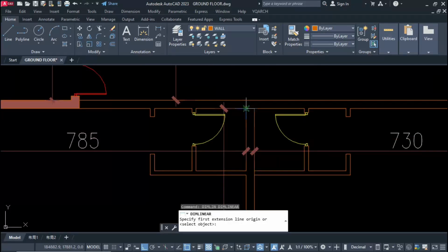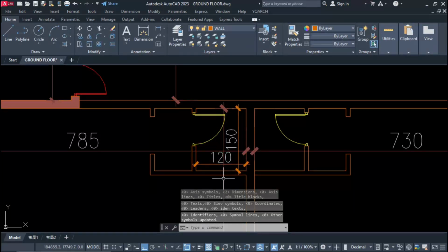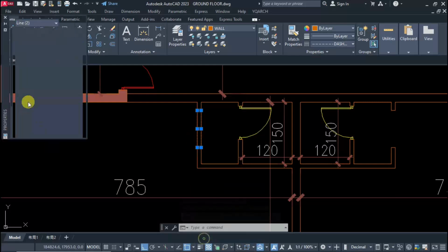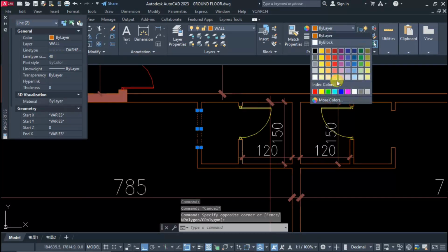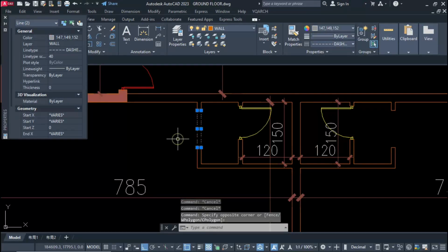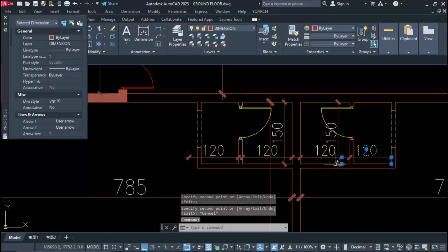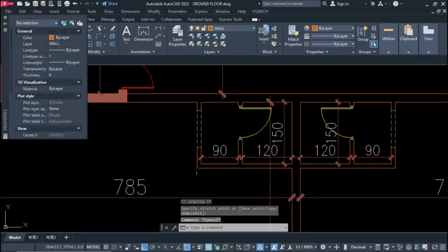This is okay, and provide dimension. You can scale simply by the ST command by clicking over. Let's mark the lintel area with a hidden line. Change the line type scale here and give a different color. So this is our lintel area. We'll open it wider. Copy again, take this reference, and here also. So this area will cover the pantry and one toilet. Good enough, this space is good enough.